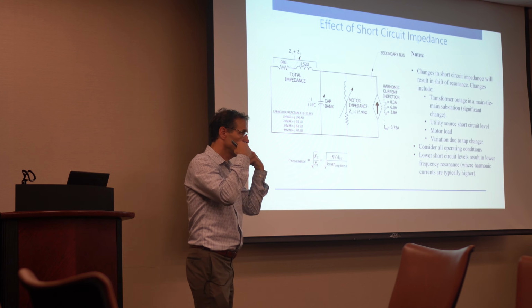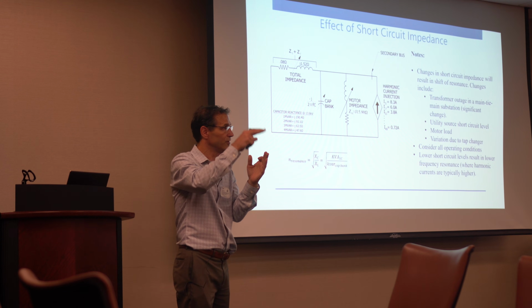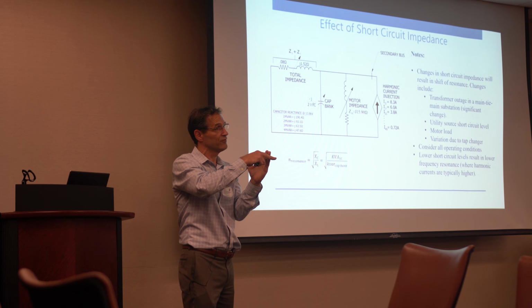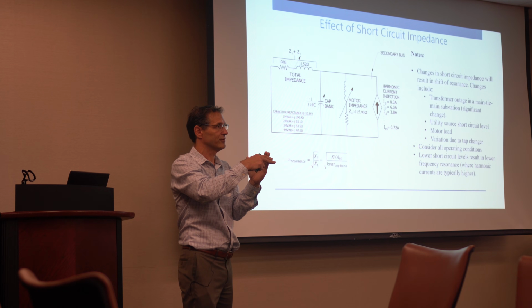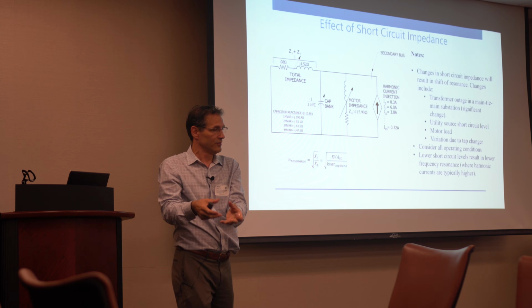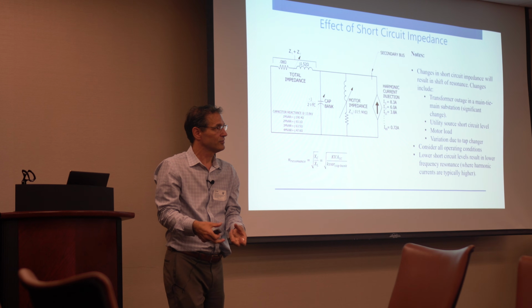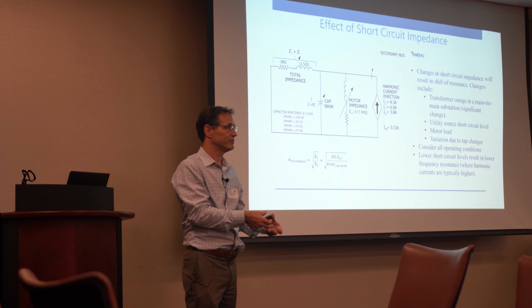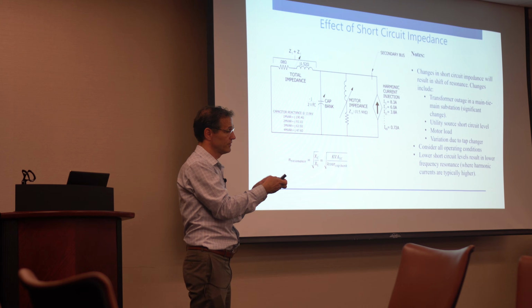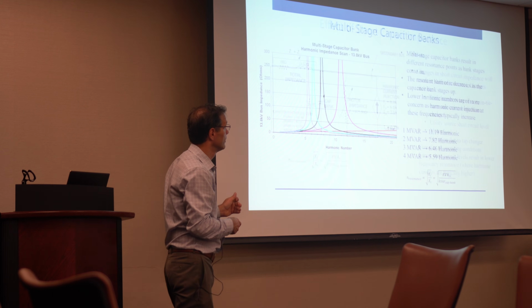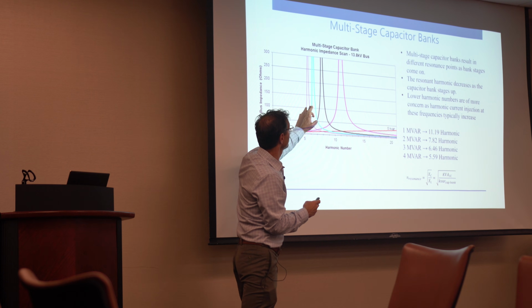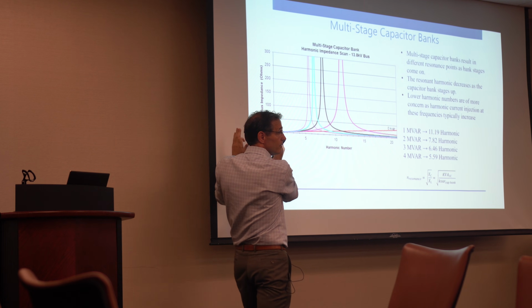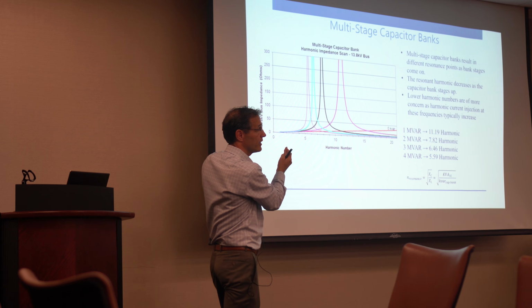But if you were to take a look at the impedance scan and you saw a resonance at 5.59, you should flag that, saying, well, that doesn't look right. We have to be concerned about that. I know my analysis says the table is good, but when you look at the impedance scan, you should be saying, if I were to shift this to the left a little bit, it's going to have the same shape. It's just going to slide to the left. If it goes over the fifth, I've got a problem.